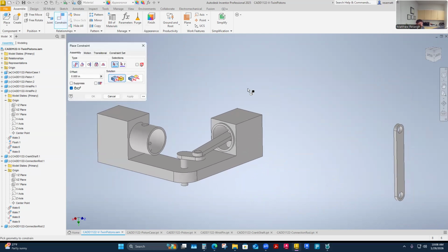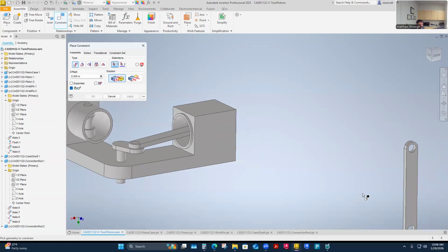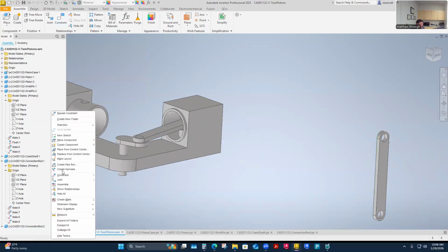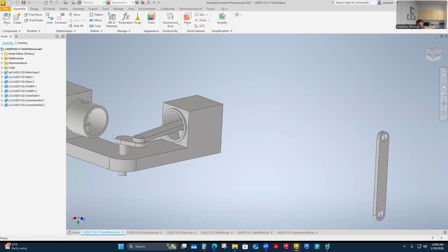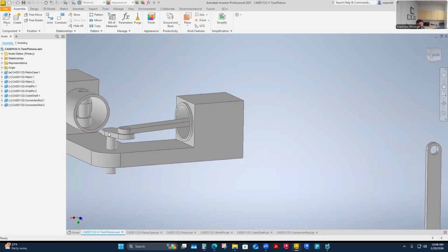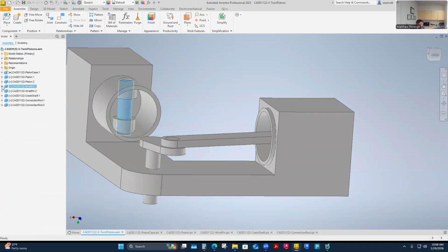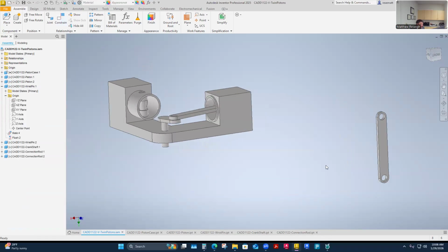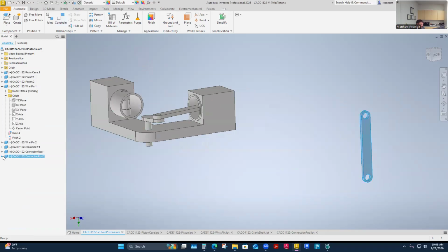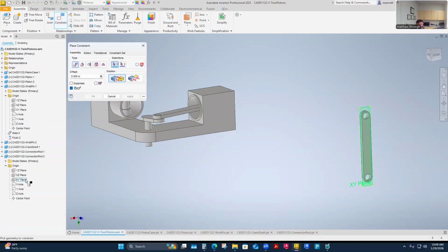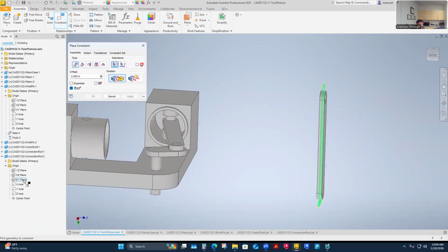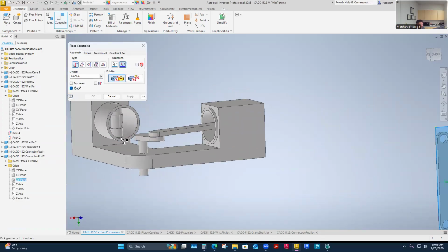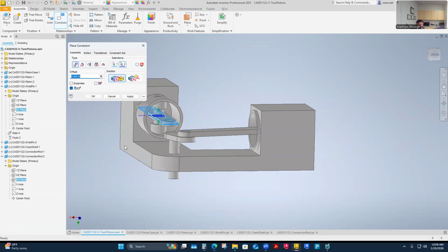So I'm going to constrain the planes on this wrist pin to this one here. If I need to identify those, just a quick collapse solve here. Here's my wrist pin part. It's this one. Here's its planes, so I have them exposed. And then this one here is the other connection. I'm going to come here with its planes exposed. I'm going to do a quick constraint on the correct plane. It's this one. Going to constrain to this one. Snappy.